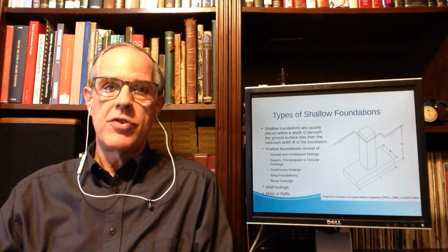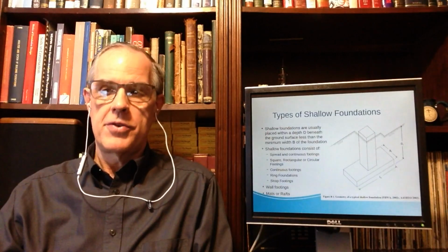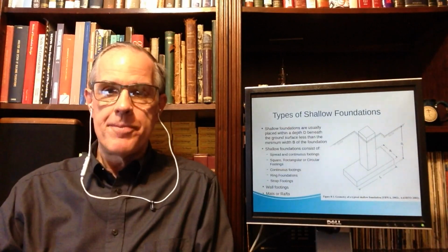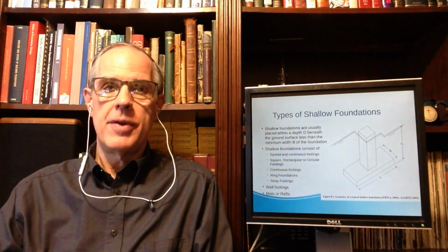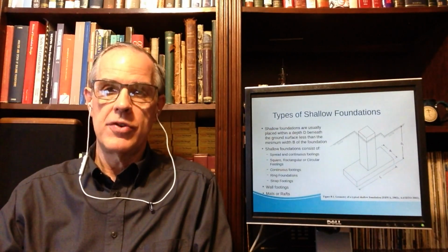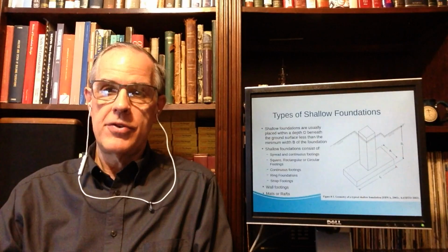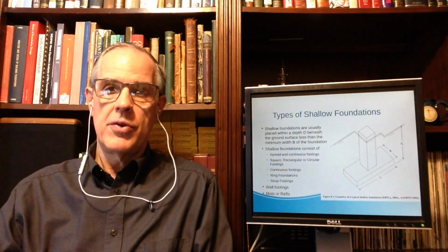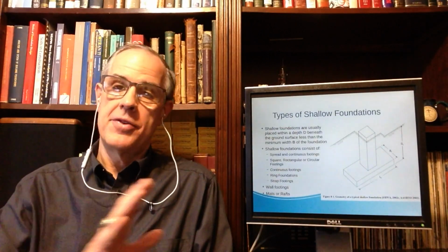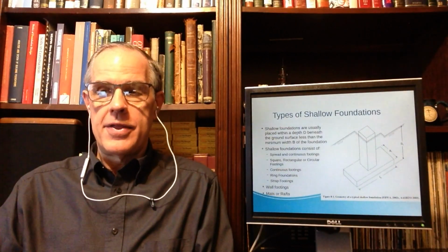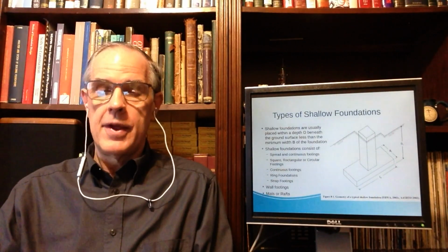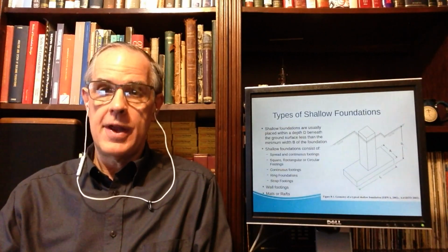Most shallow foundations are placed at some depth beneath the surface, and generally speaking, that depth, D, is less than the smaller dimension of the foundation, B. You remember we had B and L when we talked about elastic solutions, and I said for elastic solutions they're interchangeable, but as a general rule, discipline yourself to use B as the shorter of the two and L as the longer of the two. That discipline will definitely come in handy here. Also note that the depth is less than B, but there is a depth.